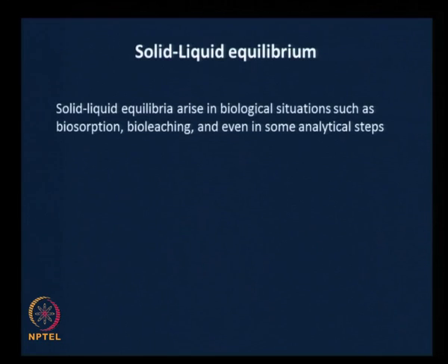For example, when there are toxic trace metals present in, say, an effluent, one of the ways by which they can be removed effectively is by contacting this liquid phase with another solid phase into which the metal can partition. Therefore, there is a huge reduction in the volume that contains the metal, and therefore better processing capabilities later.